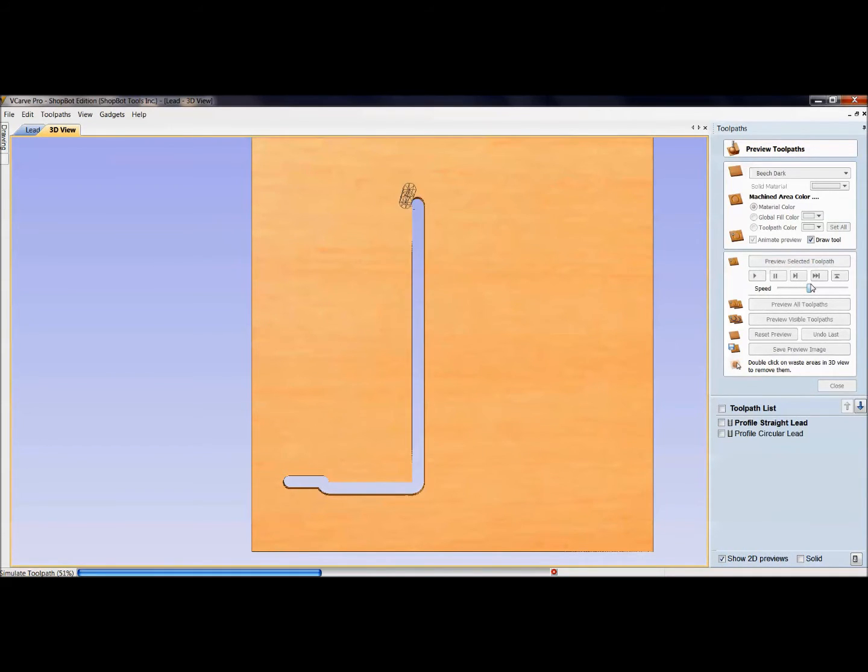and then we'll come back around. And we could also give it an option to lead back out if need be. Now that did not have a lead out, that ended right there. So that bit would have picked right up, which on our example of our project that we're going to be working on, this would not have worked. This would have either broken the bit or wrecked our material.